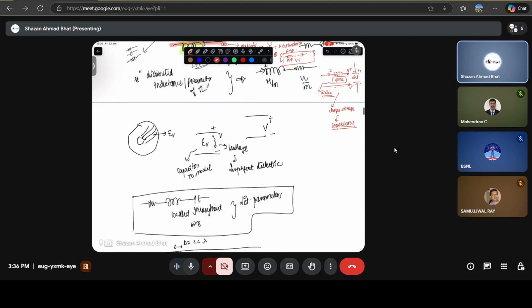Just like in a diode, you know that if this is a P, this is N, you have positive immobile ions in this region, which is basically called the space charge region. Then you know that this particular thing acts like a dielectric, and if there are charges present here, electrons on the N side, holes on the P side, this can give rise to a capacitance.